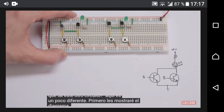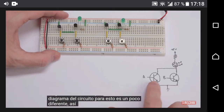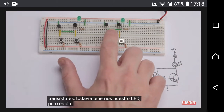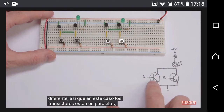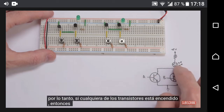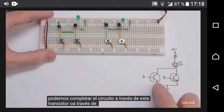I'll show you the circuit diagram first. And the circuit diagram for this is a little bit different. So we still have two transistors, we still have our LED, but they're wired up just a little bit differently. So in this case, the transistors are kind of in parallel. And so if either of the transistors is on, then the LED would come on, because we can complete the circuit through this transistor or through this transistor.